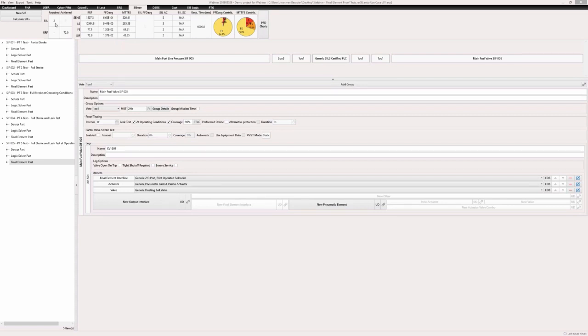So if you find a specific floating ball valve from a specific manufacturer, you may have lower failure rates. Generic data is always intended to be conservative. But let's say this is what it is. Obviously, I'm not meeting SIL 2, so there are different options. I could add redundancy. That would probably not be the most cost-effective. I can also include partial stroke testing.